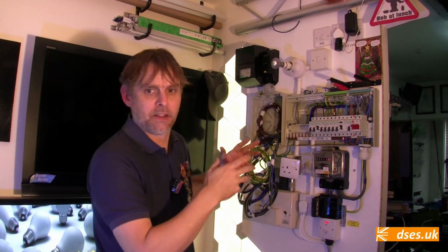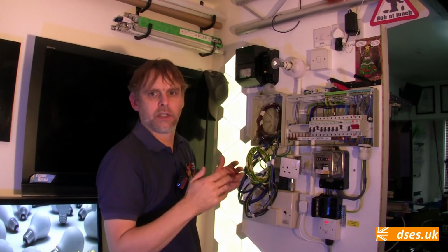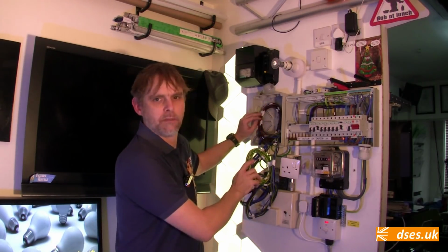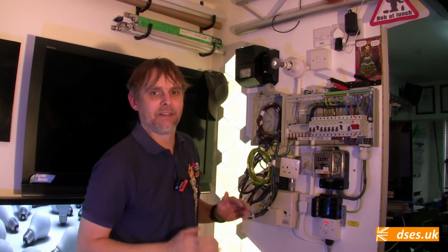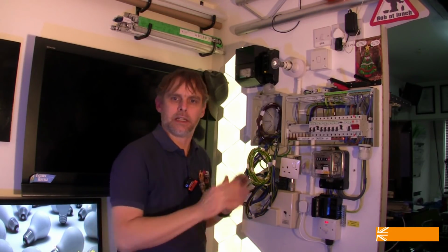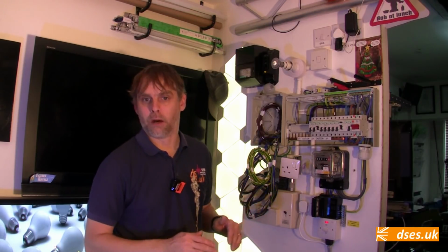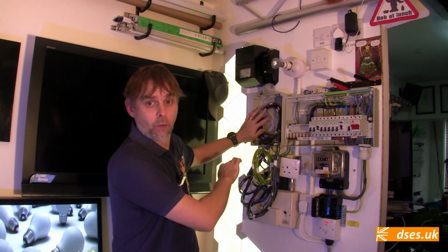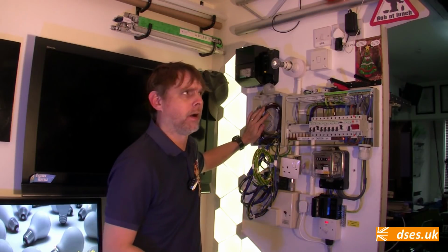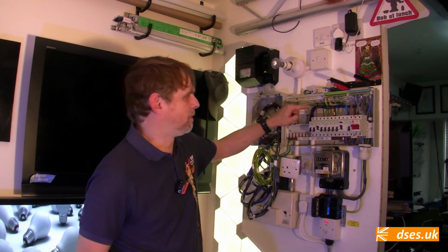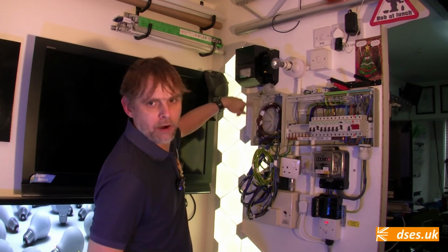for both the radial socket outlet and for this lighting point. And I then tape together the wiring for each of those circuits. So line for the socket is taped to line for the light, same for neutral, same for CPC. In effect then, this simulates the lighting and socket circuits here following the same route, but each with their line taking a different path to their neutral, as it may do in an older installation or in one wired by an asshole.